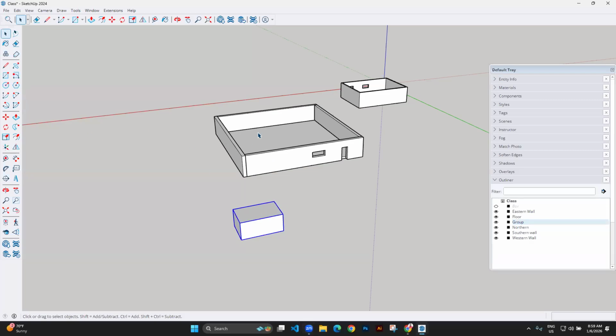Okay, so moving. If you want to move something, you can first select it, get the move tool, or you get the move tool, then you come and select it. And the better way is to select it, get the move tool. Then it's going to ask you for a base point. Remember, when you're moving something, you need to base somewhere. I'm moving this, but I could say get this corner and put it here. Now, when you're moving, make sure you move parallel to any of the axes, not like this. At least here I'm parallel to the red. I can still use arrows to fix.